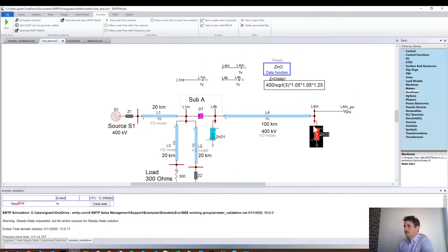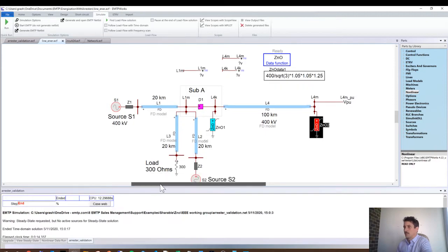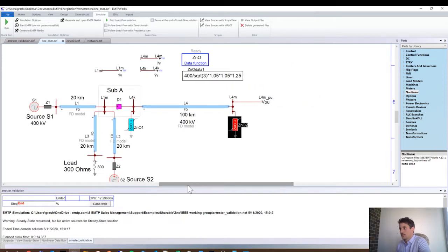One thing that you often do when you do a switching study is, first, to determine the maximum voltage. Second is to determine the energy through the surge arrestors. If you want to do things very well, you should actually use 2 different models, depending on whether you do the voltage mitigation or the energy absorption. The thing is, when you have your catalog with voltage current curves, you have some precisions in data.